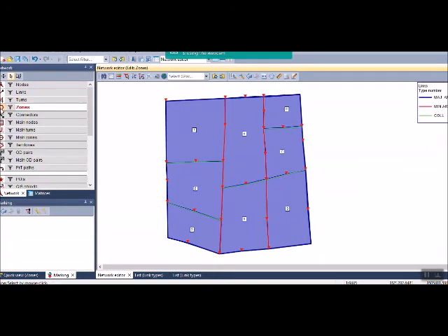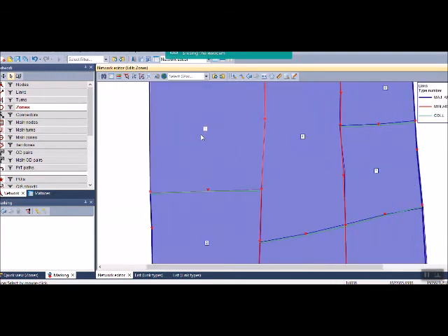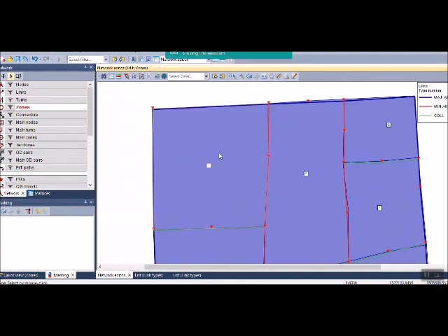Now, for sure, you can display it on and off from this icon as well. The same thing for all the items you have. Okay, the last thing is to define the connectors, which are the local roads. Okay, the local roads are assumed to allow the vehicles to move from the centroid of each zone to the main network you have. For example, I have this zone number one, and it is surrounded by some links and the nodes, which are the intersections of the road.